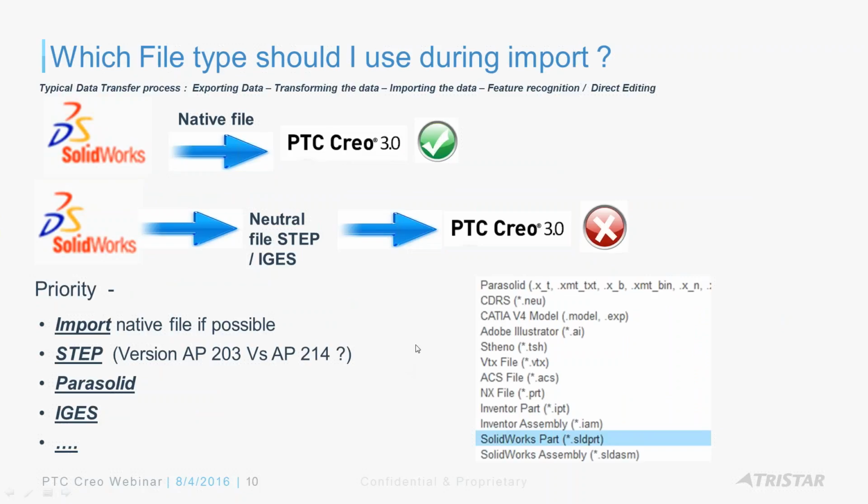Before we get into the import data doctor, it's very important to decide and understand this data transfer process. I've seen customers say that when they import a STEP file... During my industry days, STEP worked better than IGES, right? That's what I found in my experience. But could we request the native file, if available?